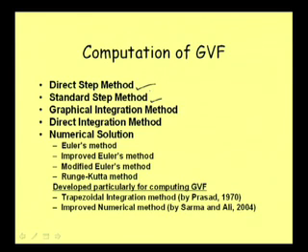The steps, that is to say the distance or length of the entire flow profile, we divide into smaller lengths, but these smaller lengths are not fixed. That we get after computation only. First we will assume that this is the depth, and then we will get the corresponding distance for this particular depth. So, that way the small segments that we get are not of fixed length.